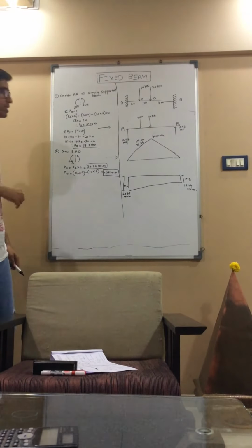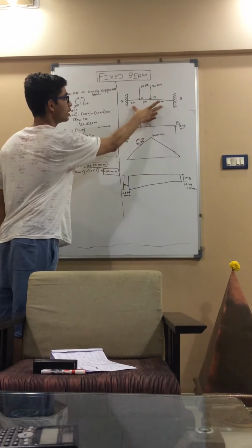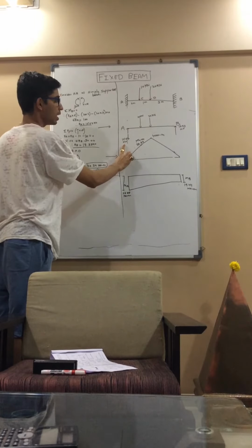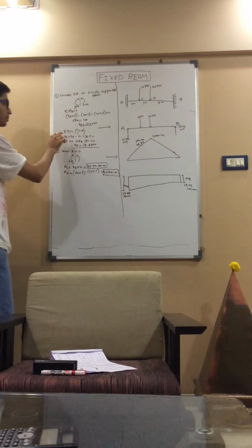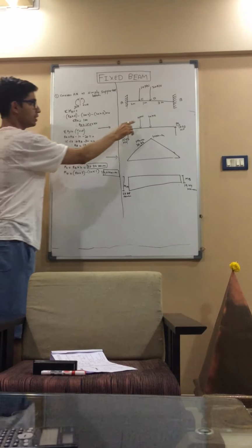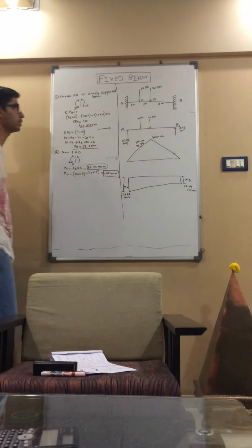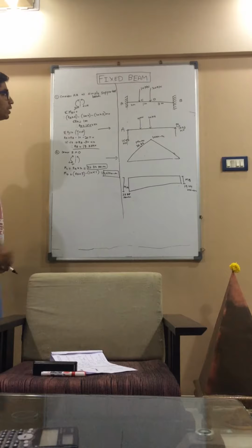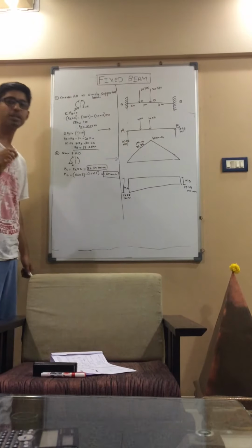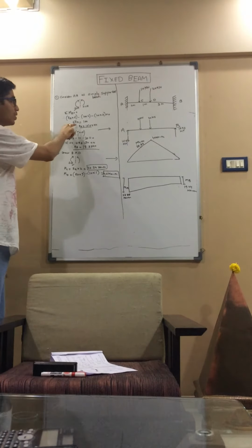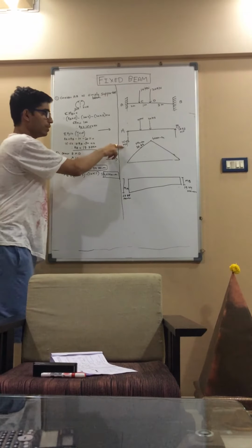So there are three forces which are acting. First, RA is acting clockwise over a span of 6 meter. So it comes RA into 6 meter. It is going clockwise towards point B. So it comes out to be RA into 6. Then this 10 kN is acting anti-clockwise over a span of 4 meter. And after that, this 20 kN is again going anti-clockwise over a span of 3 meter. So you get the value of RA to be 16.67 kN, which I have written here.